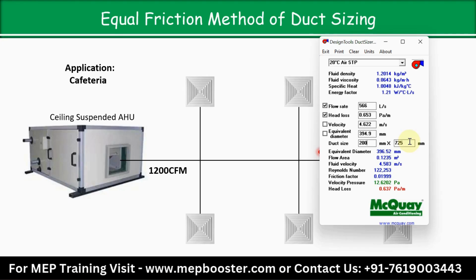Here the condition is satisfied, but the problem is, as I told you, the aspect ratio of a rectangular duct should ideally stay between 1:4, and here our main target is to always keep the ratio close to 1:1, to ensure smoother airflow, reducing turbulence and pressure loss.